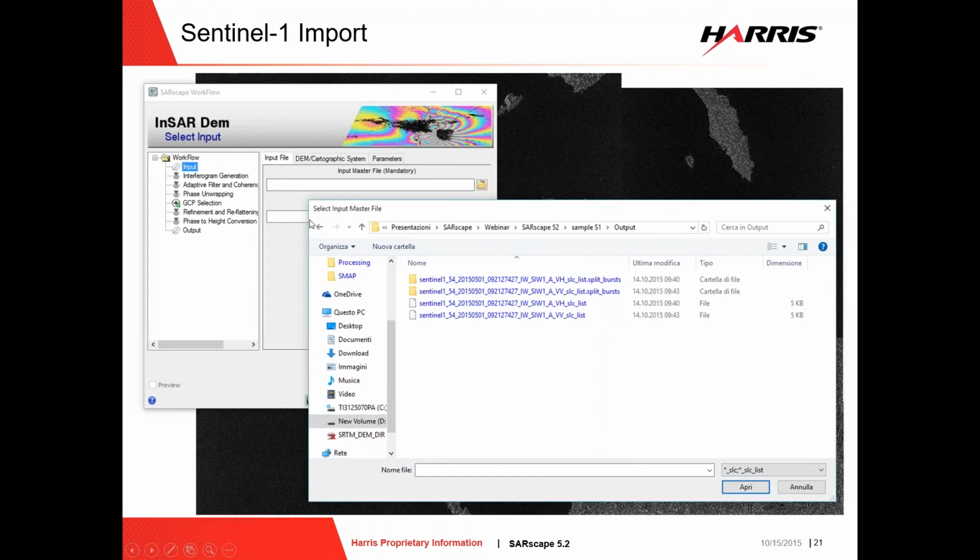So I will provide the input SLC list for my master, the equivalent SLC list for my slave, and SARscape will create all the single interferograms for the pairs of corresponding bursts obtained from the master and from the slave, and mosaic them together to form a global interferogram for all the bursts belonging to the same acquisition. So the input unit is a SLC list, but after the interferogram generation, we will go back to the image, so a single image representing the full composed interferogram for the whole area.